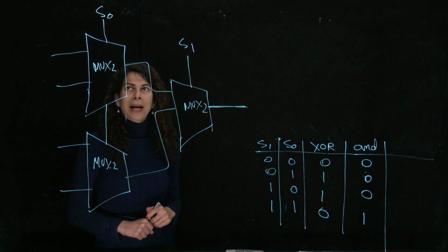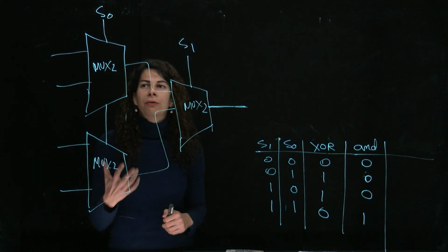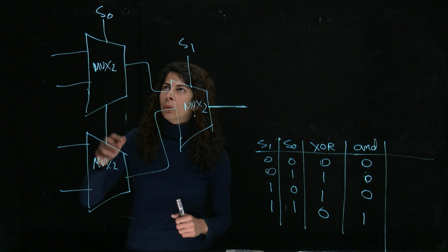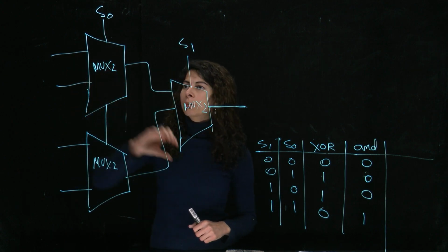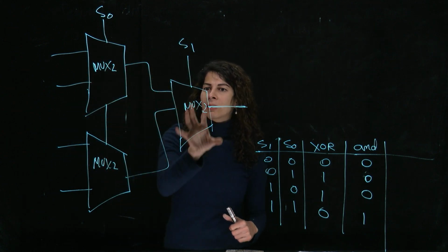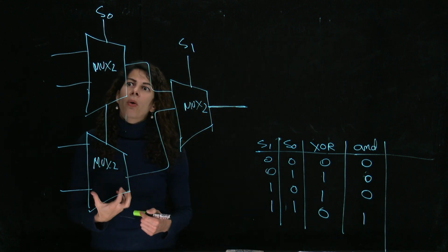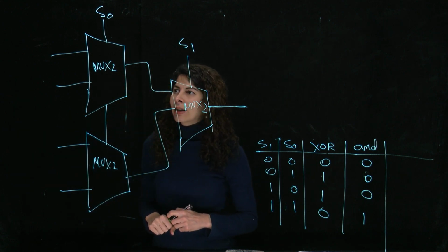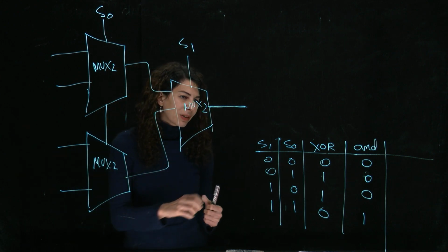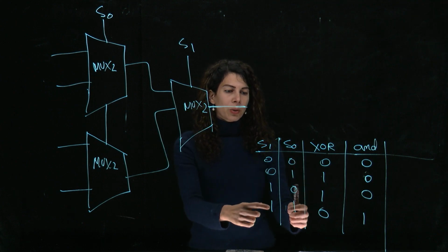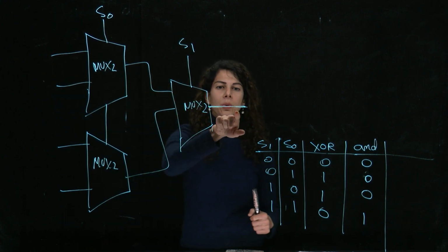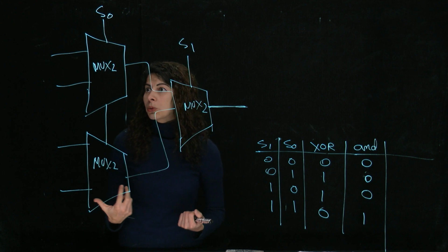Let's go back to the example we had in an earlier lecture, where we had a 4-bit multiplexer based on 2-input muxes. Here we have 2-input muxes, and we are concatenating these in series with another 3 of them to make a 4-bit mux. Assuming I'm going to use this for making logic, if the selector bits are in different combinations, they tell us which of these bits is going to show up at the output. And that we could use to implement a logic.